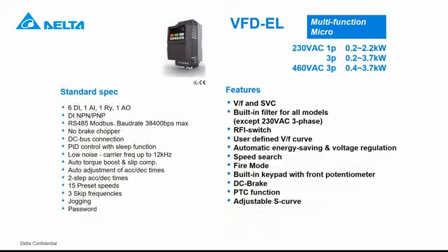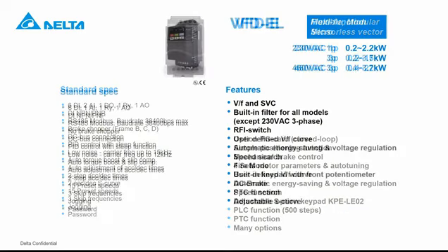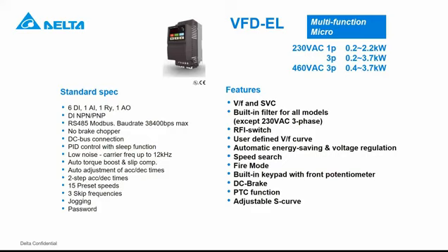And then we also have the equivalent for ME300, the VFD-EL, the micro drive. Now, compared to the VFDE, it's good to mention that VFDE does not come with a built-in keypad. So normally the keypad has to be ordered separately. So that will be this one. And VFD-EL does come with a non-detachable keypad.